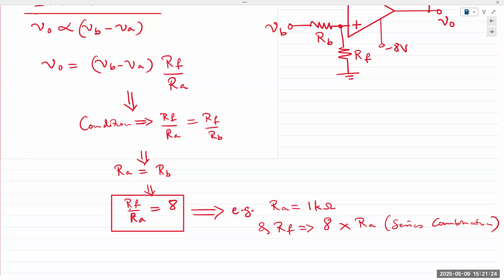Right? When you're actually designing, if you want to build this in the lab, it will work, but then you're constrained by taking actual values that are available to us. Meaning there is no such resistor as 2.6K. But if you're doing a theoretical calculation or a theoretical design, and you end up with 2.6K, that's fine. I'll allow it. In real life, obviously, you can make up a 2.6K by connecting resistors in series and parallel. And people often do that, trying to fit the design into a particular given value. It's easier to just take a bunch of components and create your own.